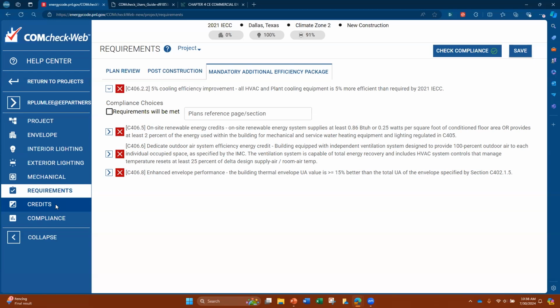But again, that comes back to what products they are using or what method they are using to meet that requirement. If it's all mostly outer shell insulation and air sealing details, they could possibly go all the way up to cladding to verify this. And then you verify it before cladding goes on, or brick or stone, or the facade goes on the front of the building. But whatever components make up this enhanced envelope performance have to be verified before they're covered up.